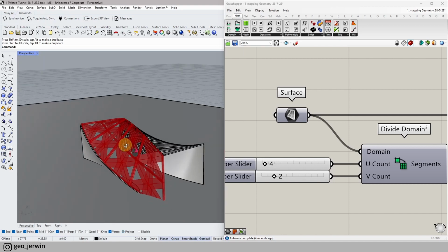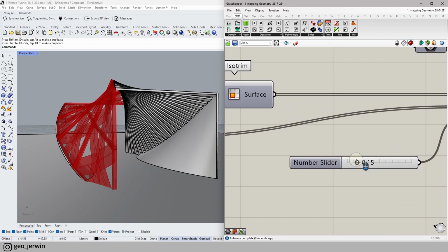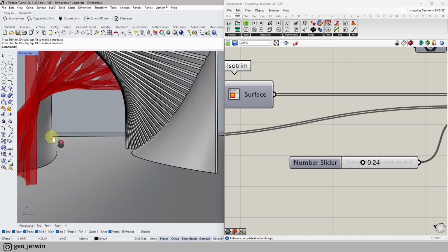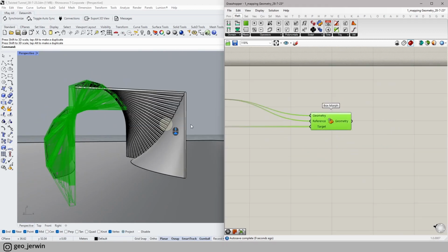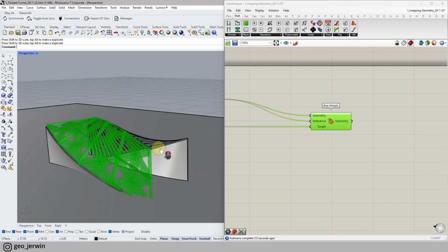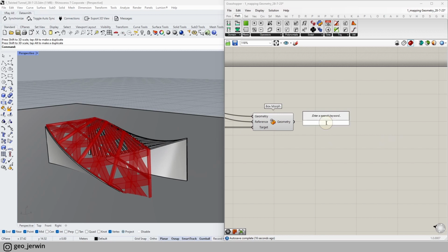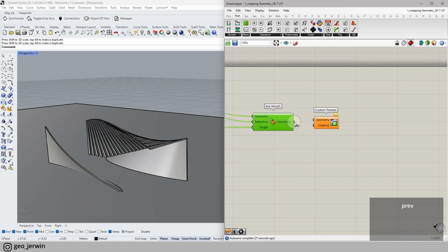All right. Now I can change the height as well here to make it a little bit puffier. All right, perfect. Now I can either export it to Rhino or I can give a material in here itself. There are two ways to give a material in Grasshopper. We can add a custom preview. I'm going to hide this one.